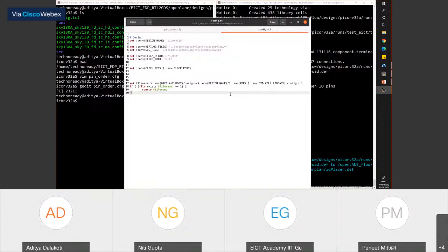Vishnuvardhan is asking whether the only way to set ports is north, south, east, west, or whether the direction can be set like bottom, top, left. It depends on what terminology the tool manufacturer defines. With respect to OpenLane or OpenROAD, which it uses, they define the terminology north, south, east, west. Usually that is the terminology used by standard as well. Top, bottom, left, right is usually confusing: top of what, bottom of what? It's just a terminology pick, and that's all the tool understands.